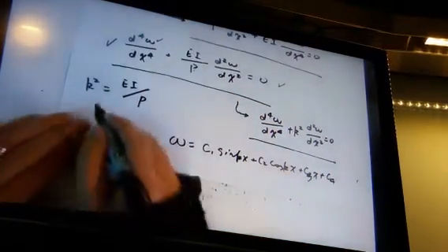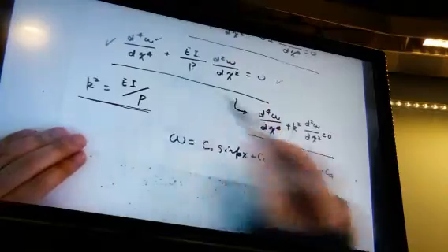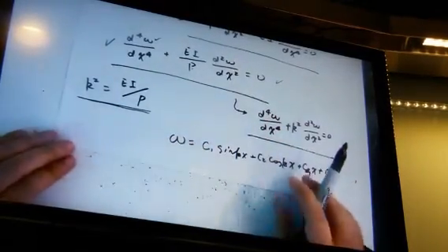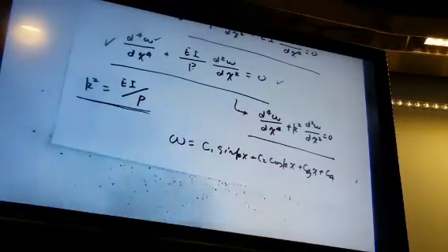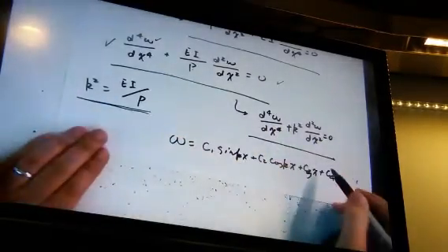And then we define a constant, k squared equals this one. The coefficient will be rewritten as k squared. So last time I got a question asking what is k. This is k. We define k this way. k is a function of Young's modulus, area moment of inertia, and the critical compressive loading. Okay. When you define k this way, you can rewrite this equation.